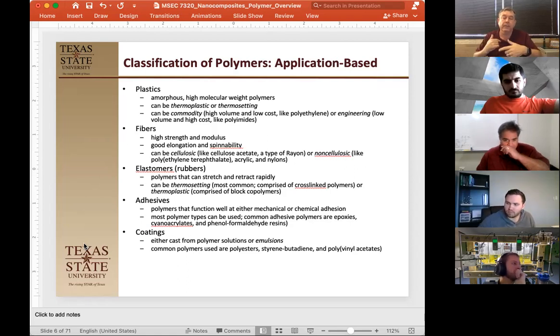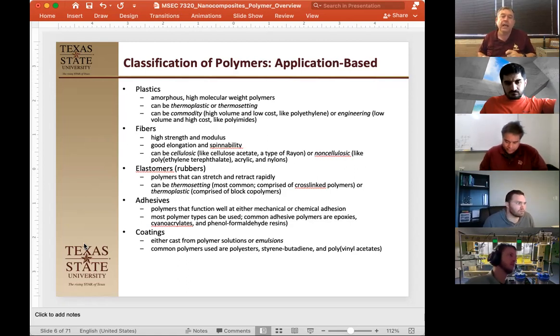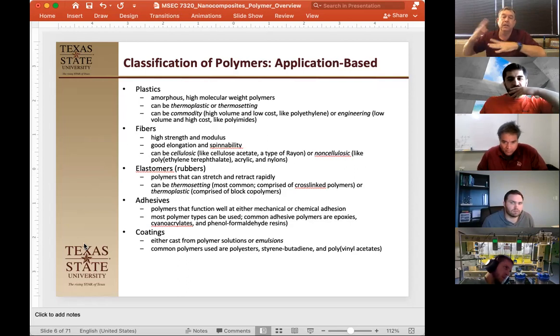So then another way we can use them is as an adhesive. And we have several different kinds of adhesives we can use. That functions either as a mechanical adhesive, where we think of something like an epoxy, which fits inside any surface irregularities and forms this hard mechanical feature. Or we can have chemical adhesion. In the case of chemical adhesion, you could have silicone on glass. Glass is almost perfectly flat. And so the silicone is chemically bonding reversibly to the surface of the glass.